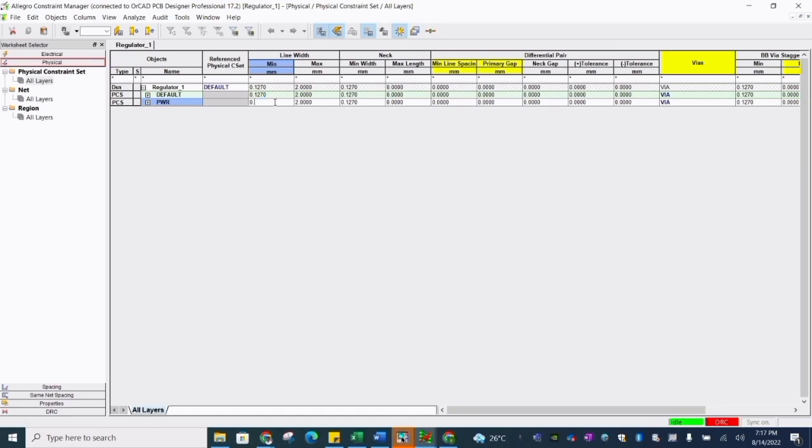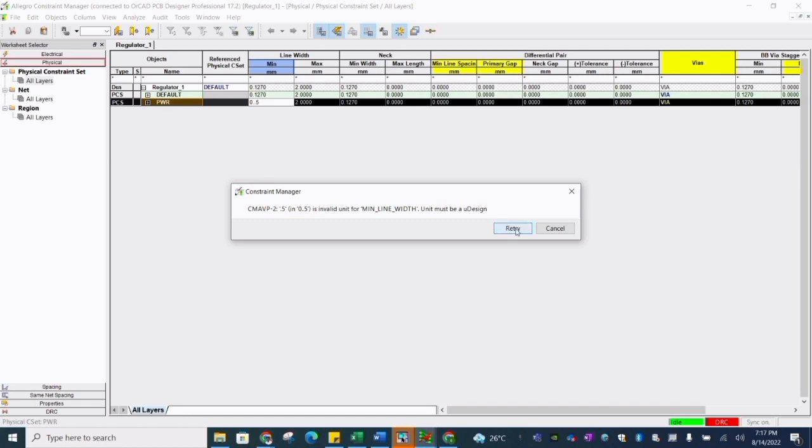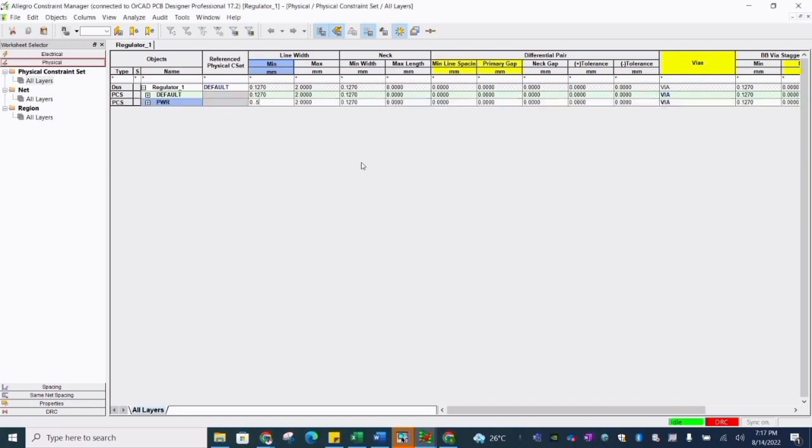So this is how you can, after import, place your components into your board outline. Now trace width. For power I'm going to use a thicker trace width. 0.5 mm is good for me, so I'm going to select 0.5 mm. So I have selected the power net.